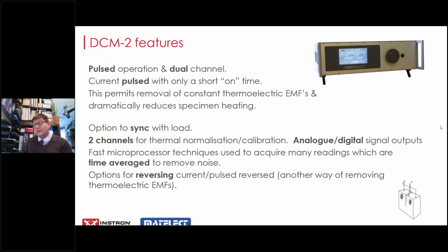So coming on to some of those techniques that we've introduced into the DCM2 to really boost how we keep the noise quiet, I think we need to look at some of the issues with developing a PD signal. The first one is, in an ideal situation, to get a large voltage on your specimen, meaning that it's noise-free and easy to read by equipment, you need a very large electrical current.